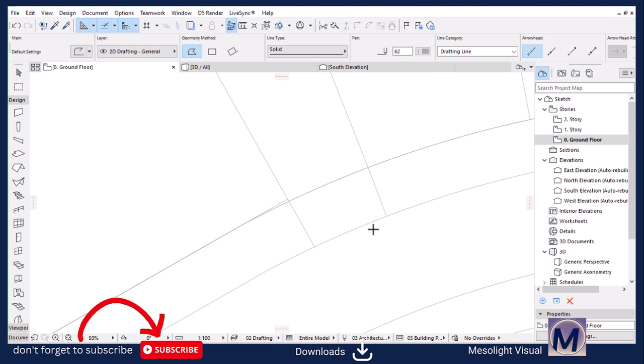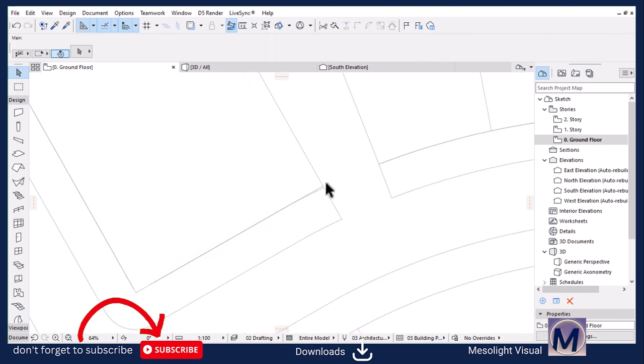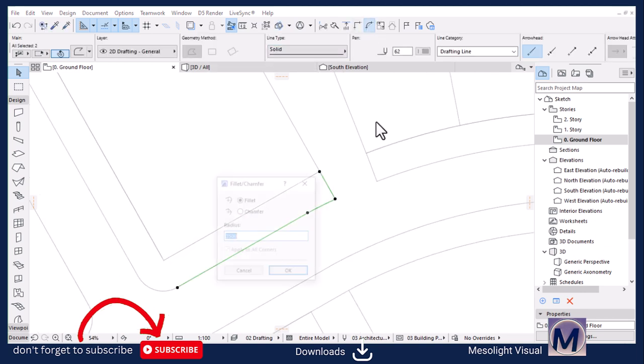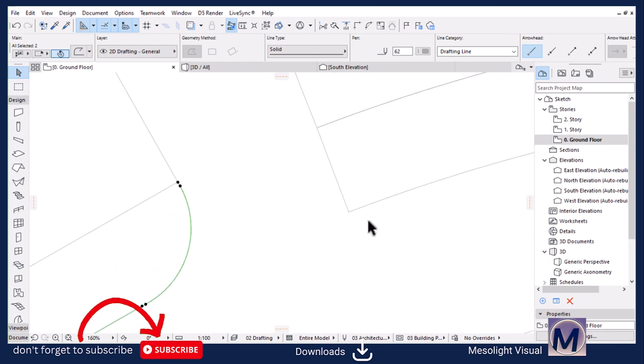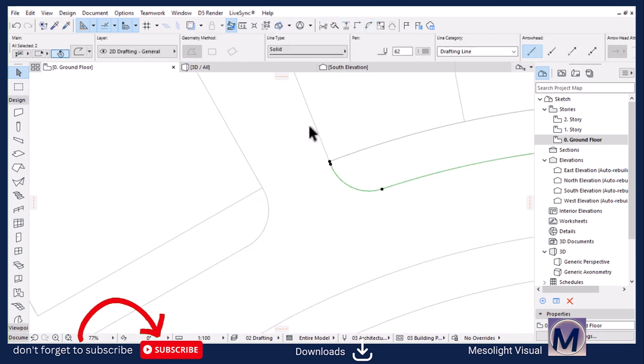Same applies here. Select all of them, and then activate trim on your keyboard. I think this line needs to go. I'll get rid of it, or they are multiple. Perfect. Then I'll select this, go to fillet. Let's try this and see. Perfect.